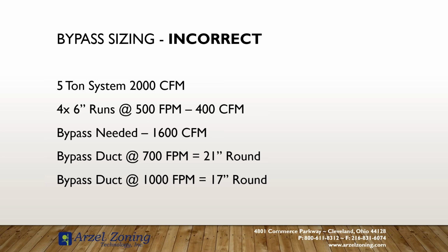So if I had a small zone, I'm trying to maintain that 2000 CFM through there, which we're really not, but this is how it would have been designed back in the day. And this caused short cycling, this caused poor performance, this caused problems with the equipment.